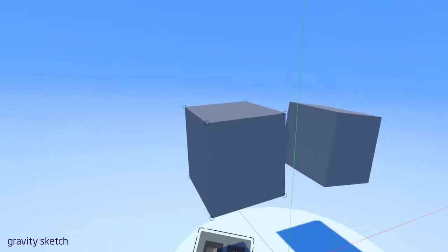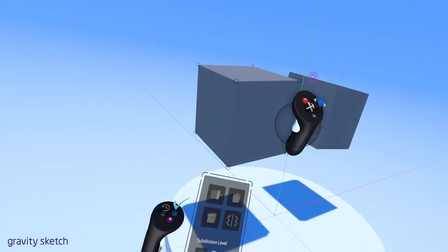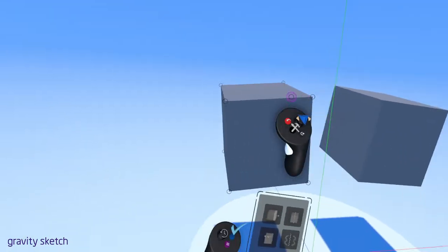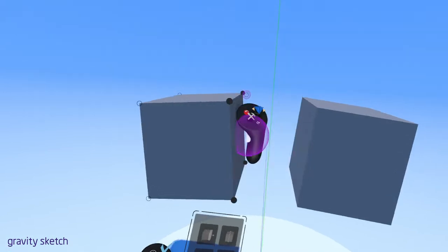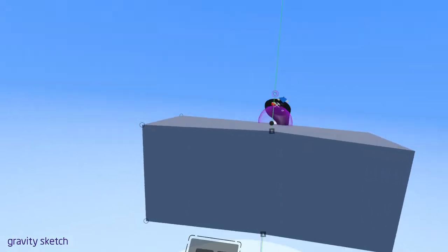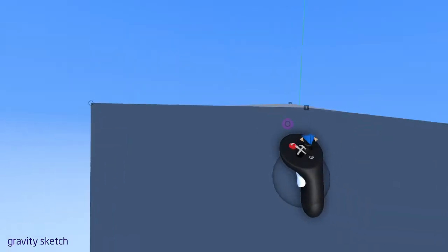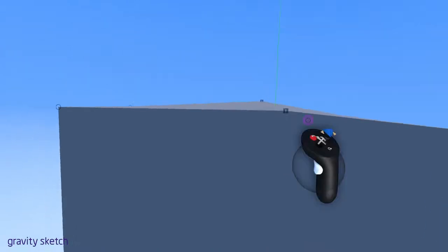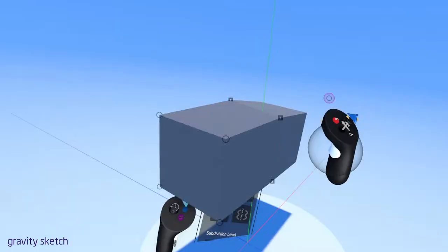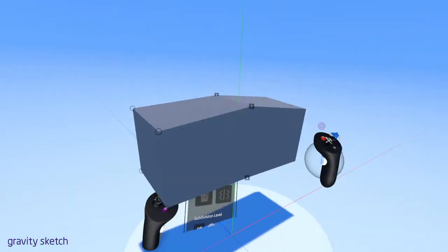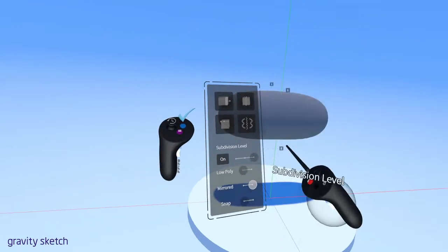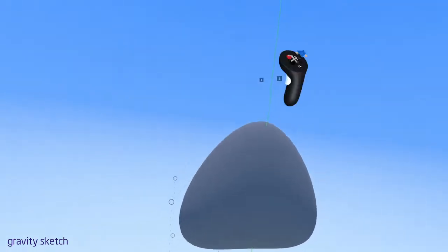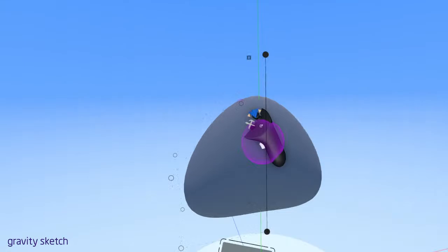it looks like something you might see, or geometry you might see in something like Maya or Blender. So you have your edit points, your faces, and your edges. And we can just continue to move these around and shape our object. And we can also connect them across the mirror plane by just dragging them to the mirror plane, and you'll see that your edit point changes its graphic to this solid black square with a keyhole cut out. And basically what that means is you're connected across the mirror plane. And what's nice about Sub-D is, if I turn on Subdivision here, you'll see we have tangency across the mirror plane. So I have a nice curved shape and there's no peak there.